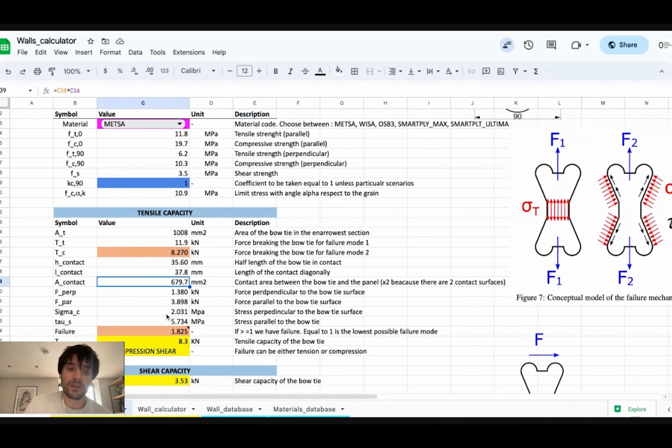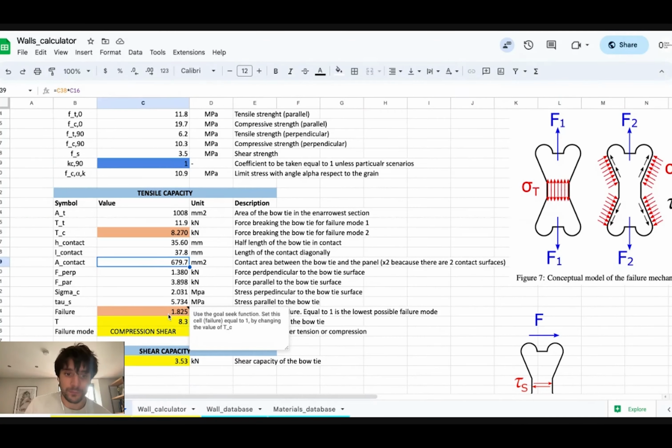There's a formula in the Eurocode 5 which takes the compression force divided by the allowable compression capacity plus the shear stress divided by the allowable shear stress. When the sum of these two components is equal to 1, then you have a failure. There might be other failure criteria that you can specify, but I thought that was the most straightforward among all the available ones.